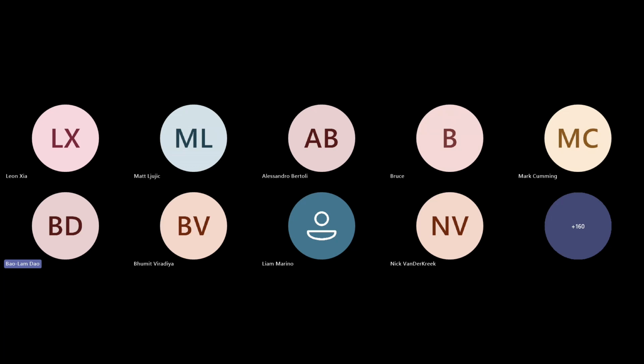He's asking about how the software deals with minimum design actions according to AS 4100, which I've replied to, saying that it's up to the user to enforce those actions and check that all the load combinations comply with AS 4100 before analysis. But there is a little workaround in the software where they've introduced the percentage loading as a workaround to apply the minimum design actions in the software. I don't know if you want to just quickly show that, Nick, the percentage loading.